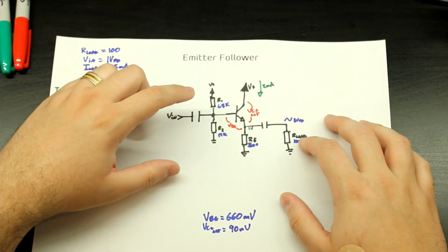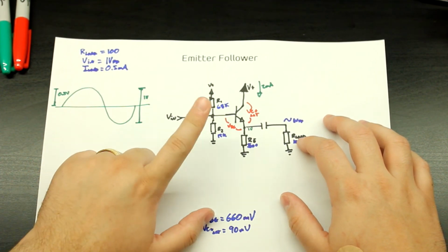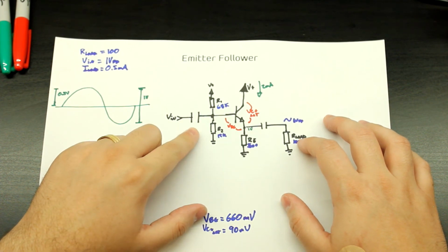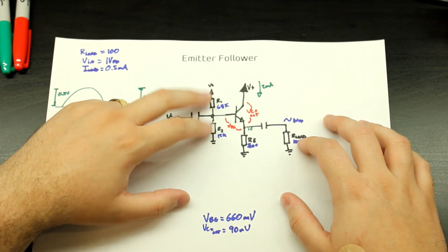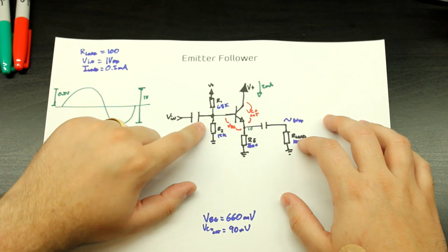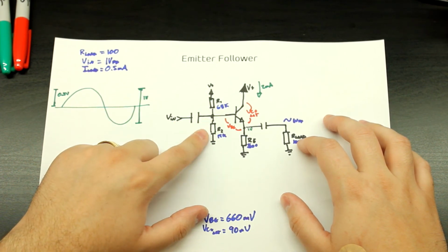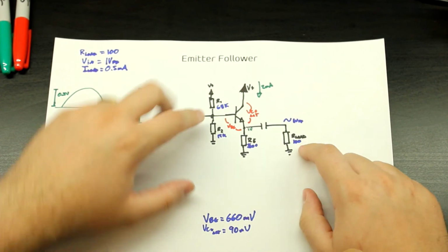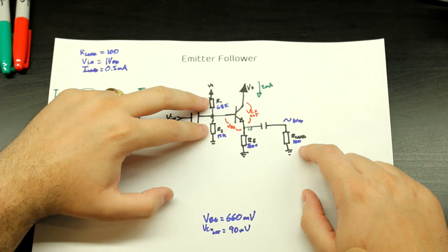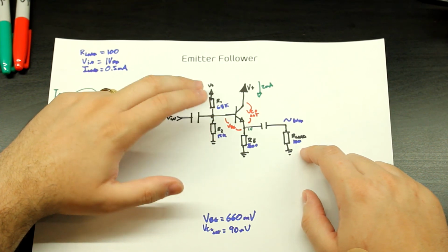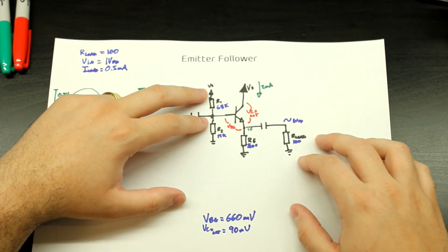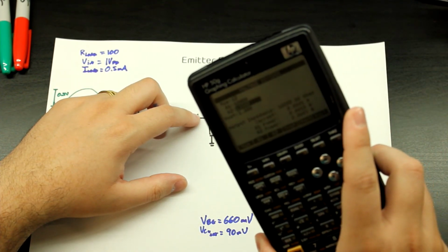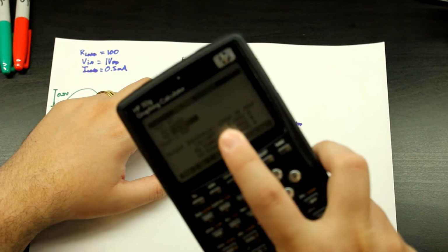So now for this capacitor, this is also going to be a high-pass filter, but this high-pass filter is going to have these two resistances in parallel. So if you want to calculate this, it's very simple. You do the same thing that you did to discover the capacitor here, but you put these two resistors in parallel. Okay, and then you get the high-pass filter that you want. In this case, my program already calculates it for us.